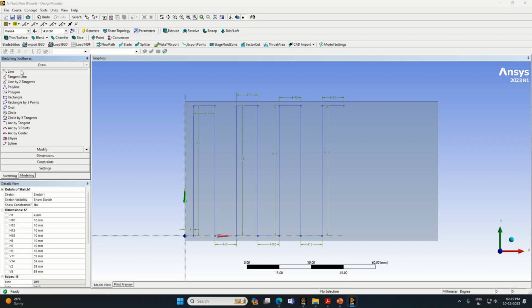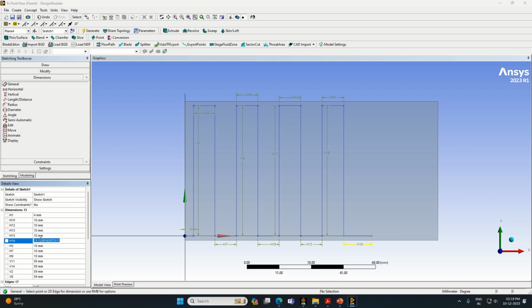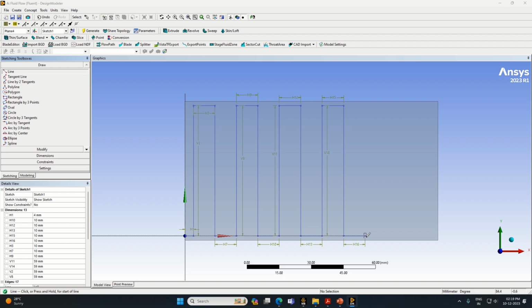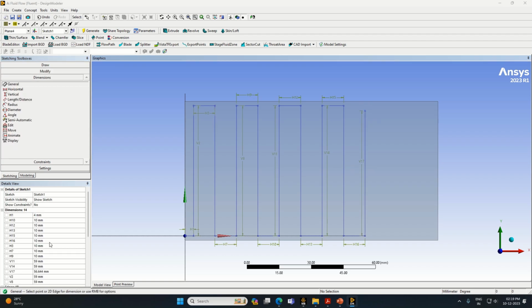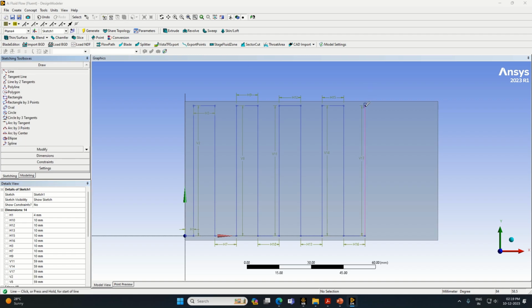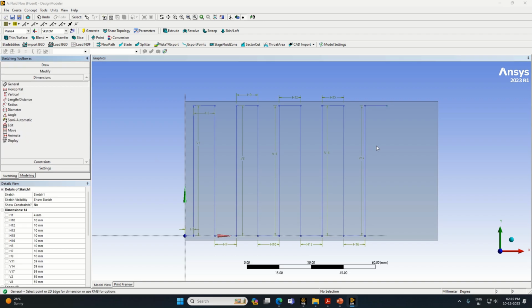So we are trying to have channels over here, that's why we are preparing the geometry sketch here. Make it 10 again. Draw a vertical line. Take the dimension equal to again 59. One more time, draw a horizontal line. Take the dimension again, equal to 10.